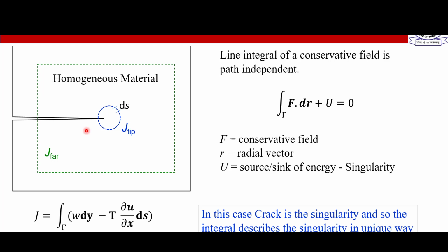So in comparison to other streams of the subject related to structural integrity, this field is relatively newer, younger. And then comes the time of James Rice, and he applies this physics that if you have a force vector, which can be defined as a derivative of a potential, and then if you take a line integral of that, you should get a value of 0 if there is no source or sink of energy inside that field. So it works also in the electromagnetic field and other fields.